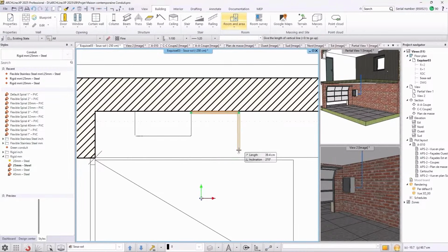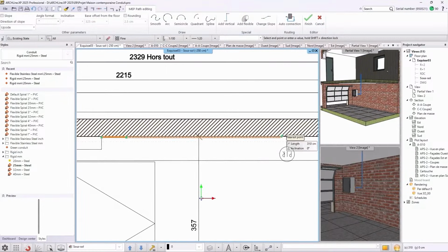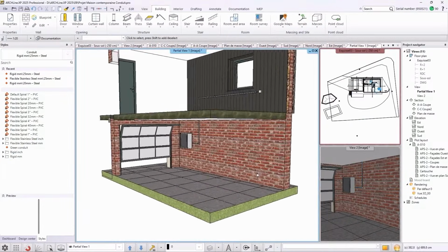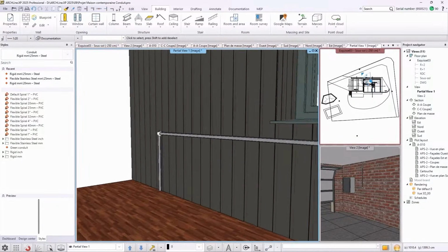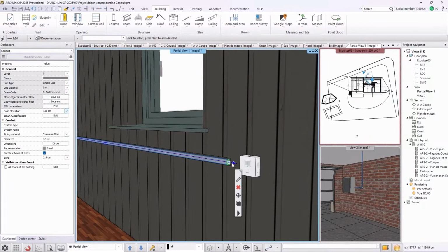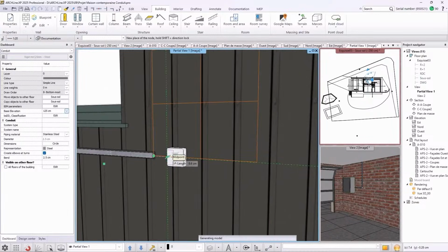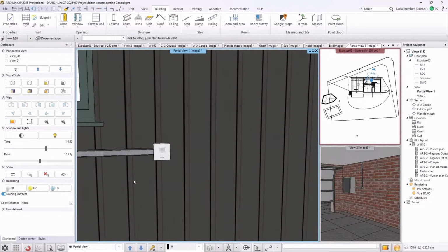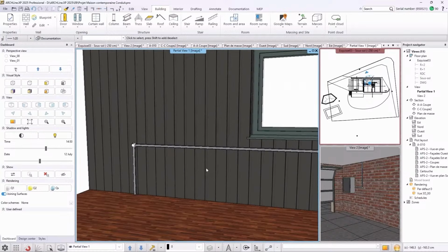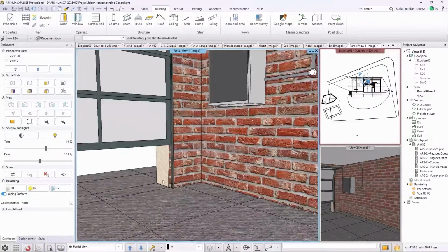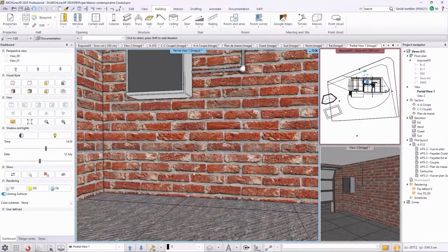When you use rigid conduits, it is impossible to flex them, thus you need to use electrical boxes at the L turns. In ARCHLine.XP, they are automatically added to the conduit, so you just have to draw its path. You can not only place conduits on the floor plan, but in the 3D view as well. Now let's place a flexible electrical conduit in the project.